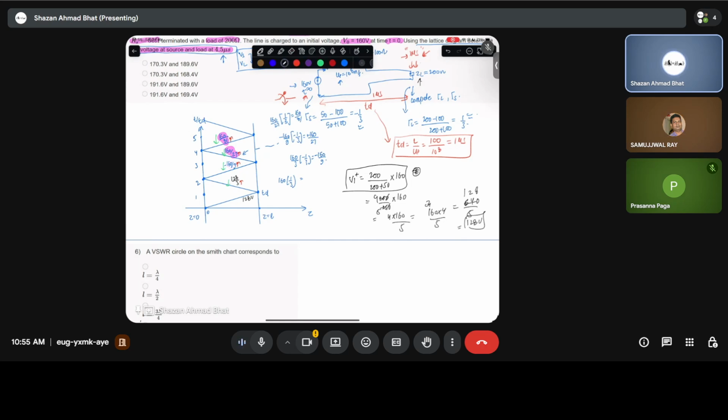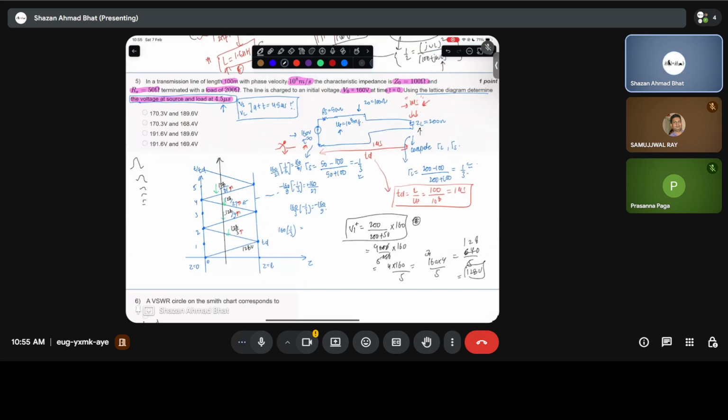So instead of 160, it's 128 divided by 9, then 128 divided by 27, then 128 divided by 81. As you go up, you see that these values are reducing. If you give a voltage pulse, then as it gets reflected, the reflection amplitude gets lower, and lower, and lower. Finally, the entire system stabilizes. That is the basic assumption of this.